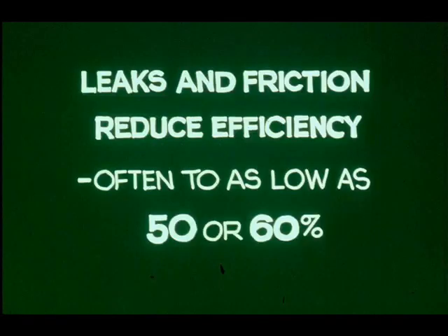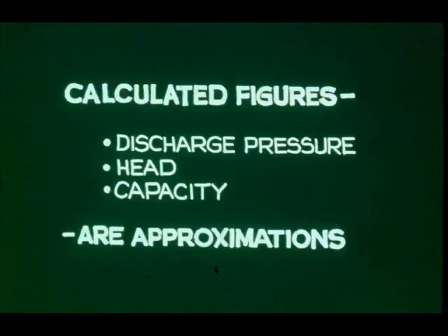Steam and liquid leaks, internal pump valve leaks, and friction all reduce efficiency, often to as low as 50 or 60%. So we must consider our calculated figures, discharge pressure, head, and capacity, as approximations. They are nevertheless useful in working with pumps.